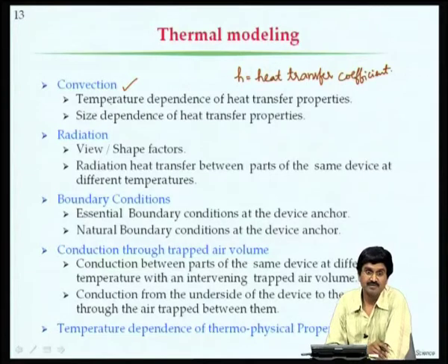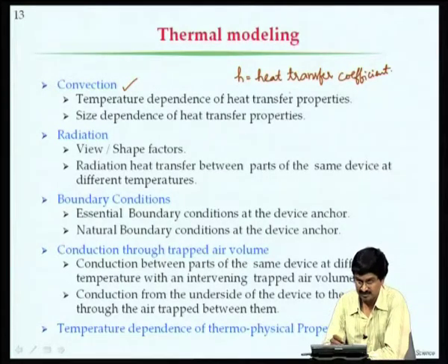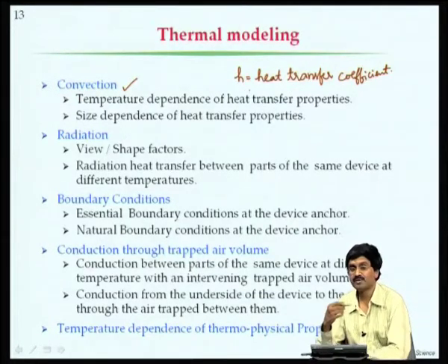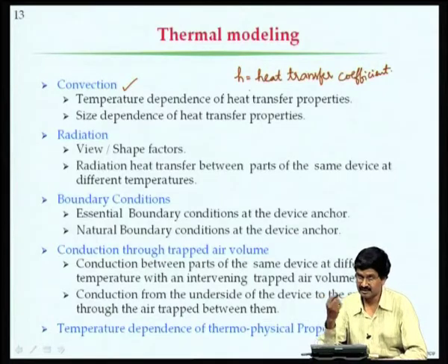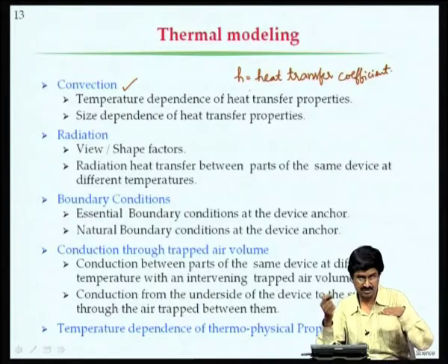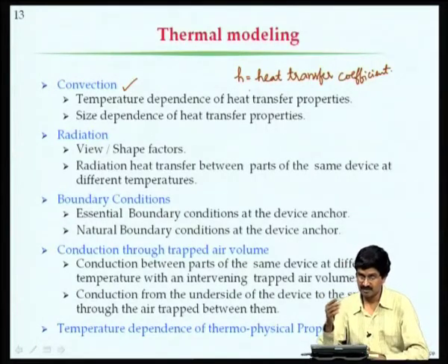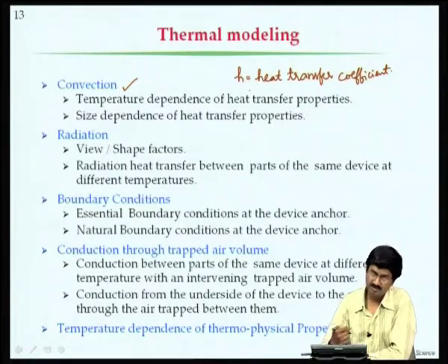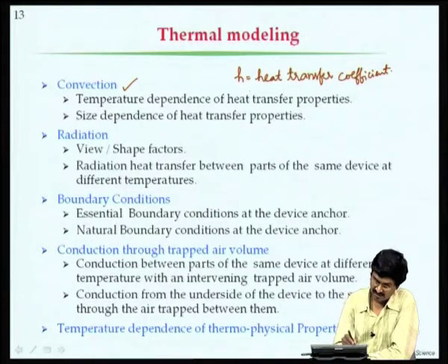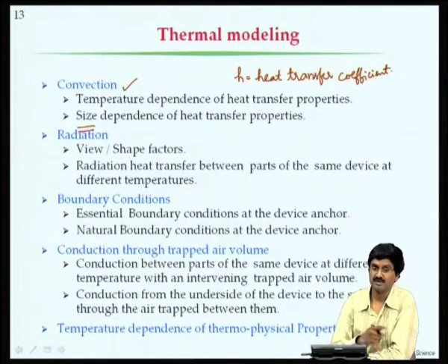Taking this convection into account is very important, and this H itself might depend on temperature, and the size also may affect this H. If you go to a handbook and try to get an H for, let us say, a plate that is horizontal, heated from above, heated from below, whatever conditions, when you take that formula for use, we have to make sure that the assumptions made in deriving the formula do not have anything to do with size. If they have, then we need to pay careful attention to that point.